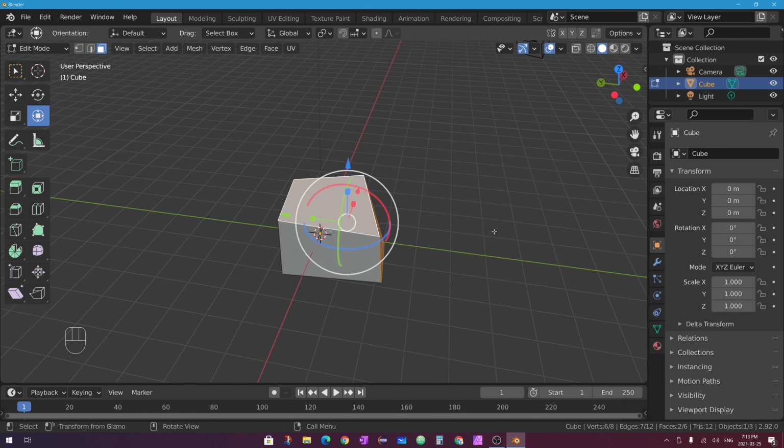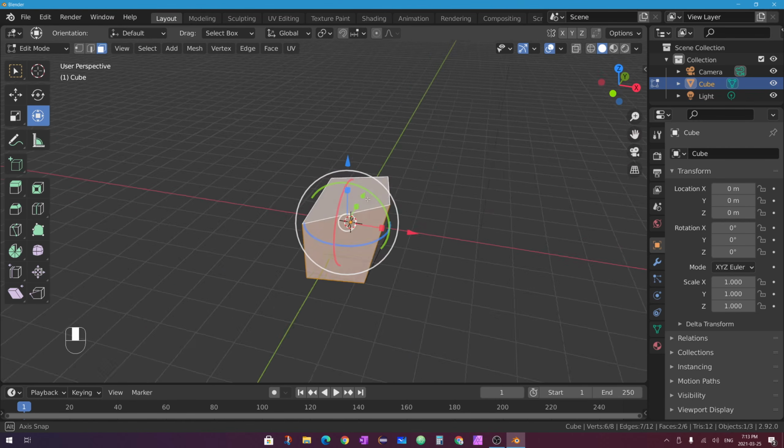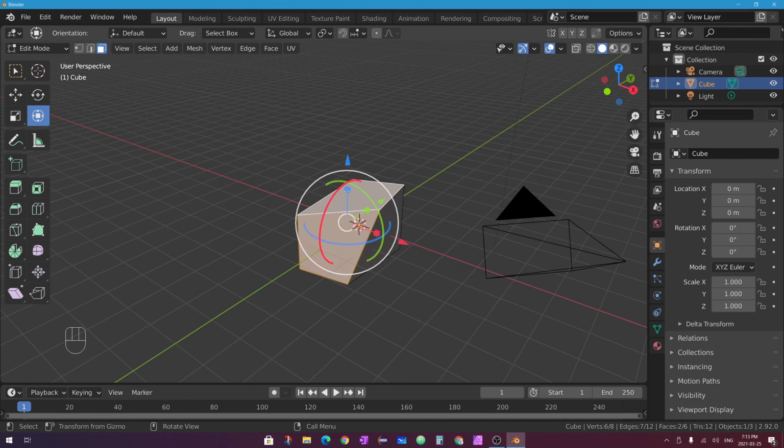So what I'm going to encourage you to do in this video is pause the video once in a while, try what I do. If you're brand new to Blender and 3D modeling, go ahead, pause the video, try going into your default cube's edit mode using the tab key or the pull down menu, and see if you can select and transform vertices, edges, and faces. Go ahead, try that out.